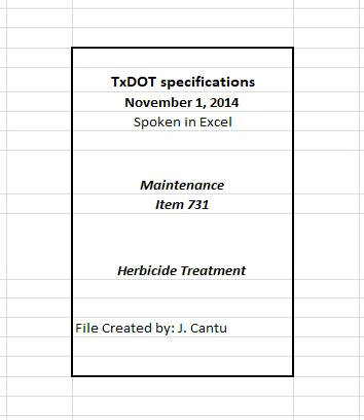6.2 Pavement edges and structures. Provide spray equipment capable of spraying a pattern that will cover cracks and expansion joints in the entire pavement shoulder and a continuous band along the pavement's edge. Provide additional booms or nozzles capable of spraying under guardrails and around signposts, luminaire poles, or other structures within 10 feet of the pavement edge. Provide equipment capable of making uniform broadcast applications calibrated at a rate between 20 and 40 GPA.